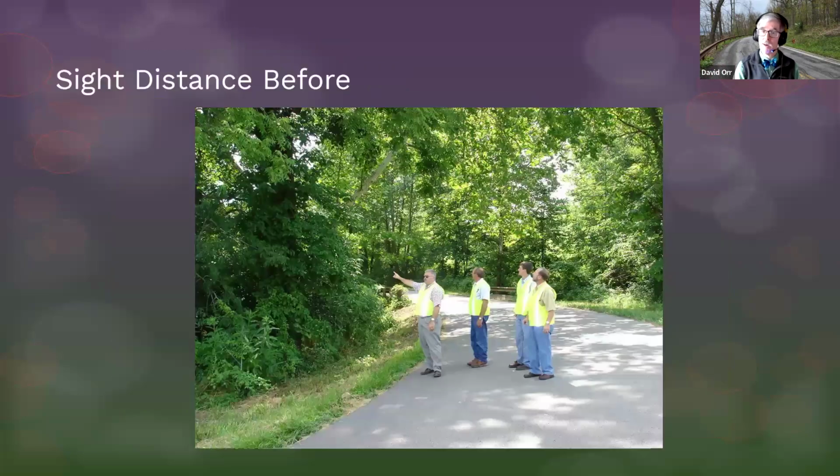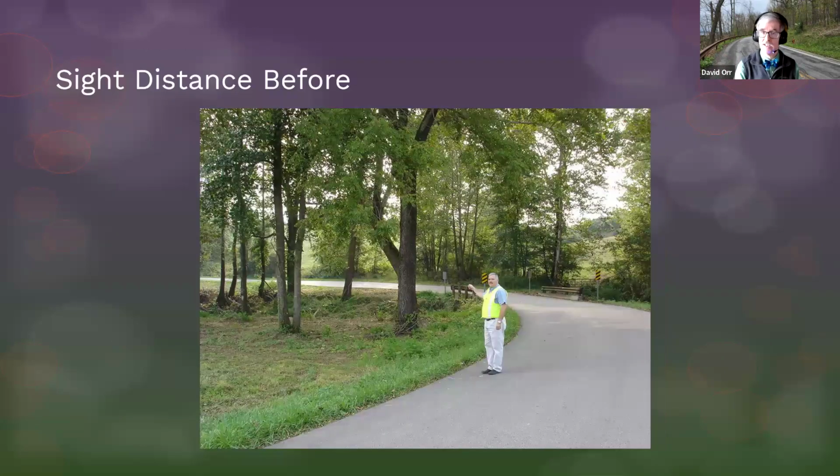And if we trim things properly, get rid of the brush and the debris, boy, we can really improve the sight distance. Now, I know we're outside the right of way, not always possible, but always be trying to think about what you can do with what you have, where you are to improve things. And by the way, we could spend a whole 20 minutes talking about the rail system for that bridge, but again, that's a different webinar. So, I'm going to give you a couple more possible things to add to your bag of tricks.